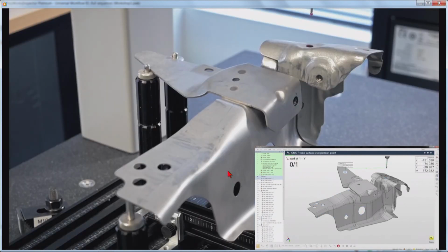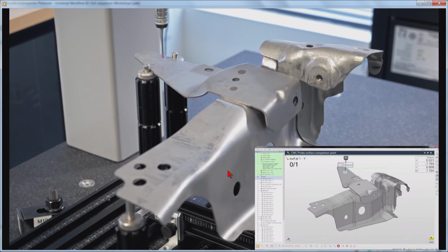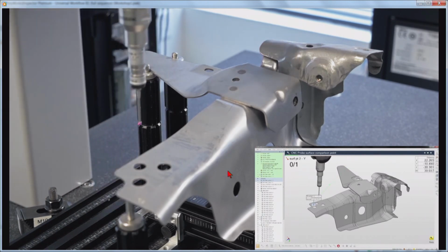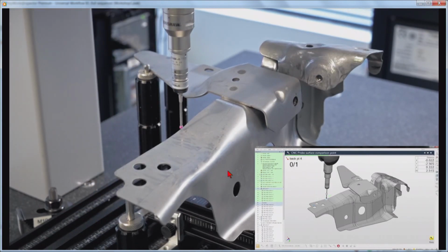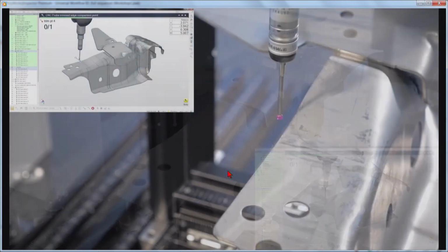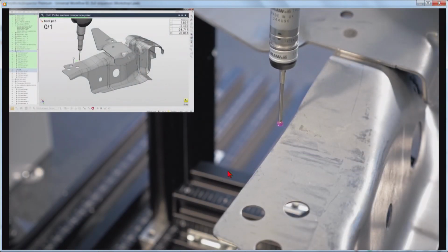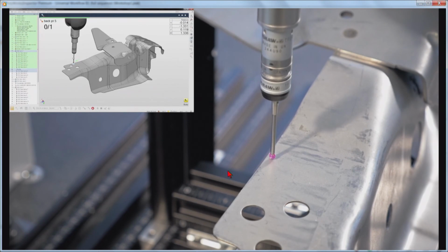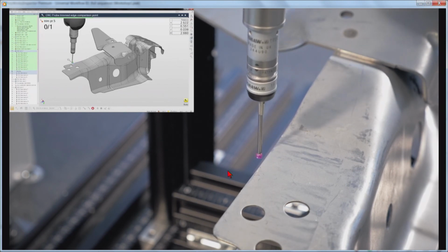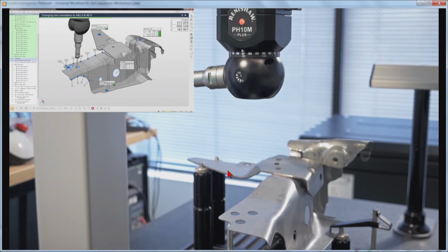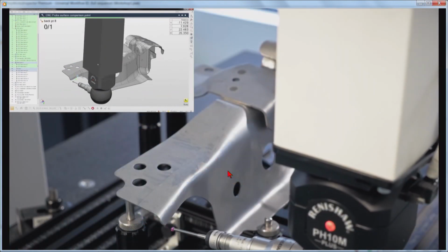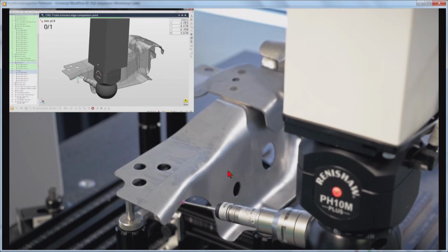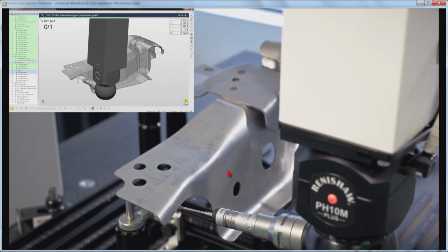And then we continue with the surface point, one at the front. And once this is completed, this is where we would do the alignment and complete whatever we need to measure from this A0, B0 orientation, trimmed edge comparison points, the holes also that we have on top, and then we change the tool orientation and we complete the inspection of that boundary, plus we measure the 2 circles on the side.